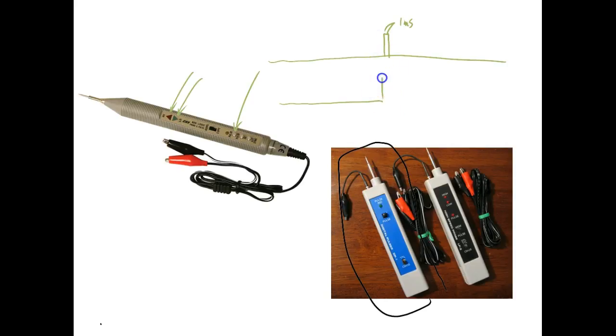So when it sees a transition, it gives us out a pulse long enough so we can see that light going. If it's sitting at a solid high, when we see the pulse light come on, we know we had a low pulse. If it's sitting at a solid low and we see the pulse light come on, we know we had a high pulse, right? And of course, if these are lit up all the time, which means you're looking at a clock, then these both will be lit up and all three of these will be lit up, indicating you're looking at a clock.